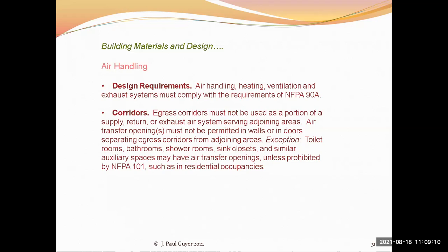Dampers also are inherently part of a contemporary HVAC system, because anytime, as an example, that an air conditioning duct passes through a barrier, a wall that is required to be of some level of fire resistive construction, 2 hours or whatever, any duct, as an example, that passes through that barrier must also have a 2-hour fire resistive construction.